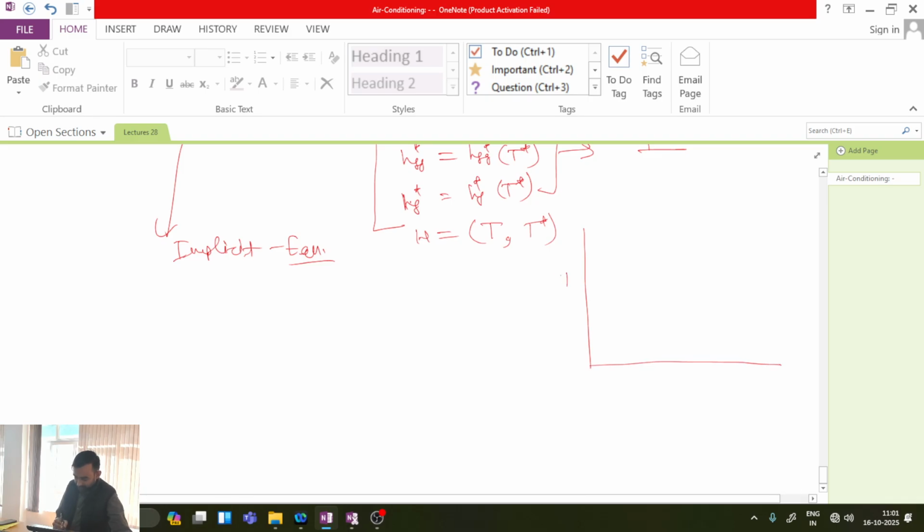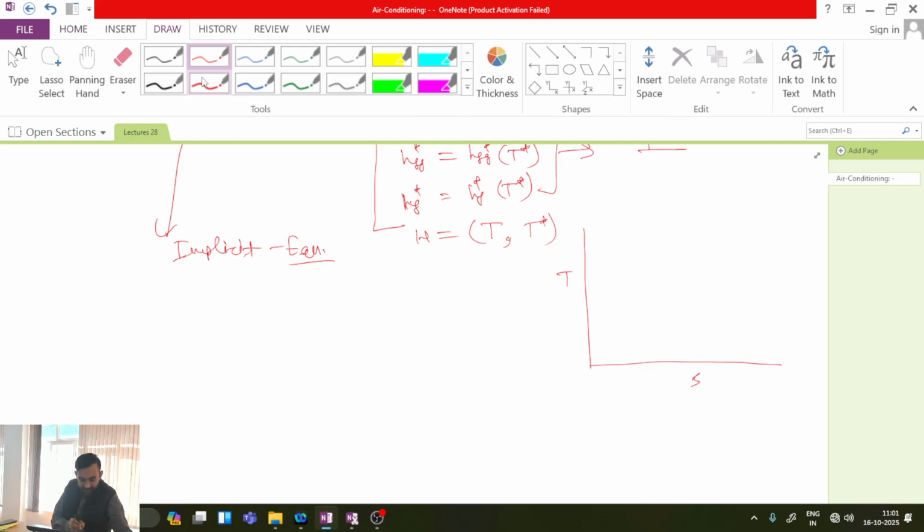even three things. If I give you the entire picture, say this is your point A. The first point was that from point A I have done cooling under constant pressure conditions. When I have done cooling under constant pressure conditions, I reached this point D, which is my TD, and TD temperature is what is called the dew point temperature. Is this one clear? So in this case, from point A to point D, temperature has decreased from TA to TD.